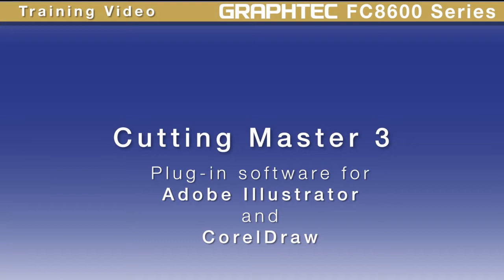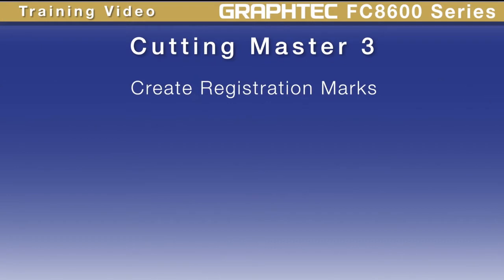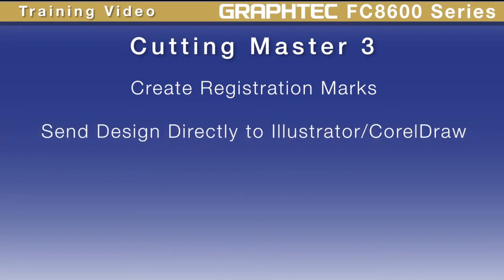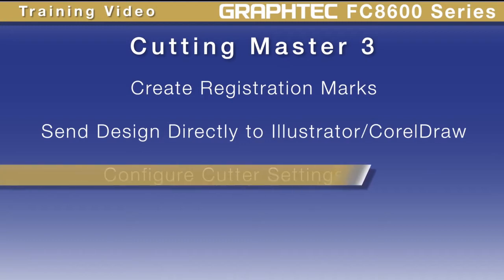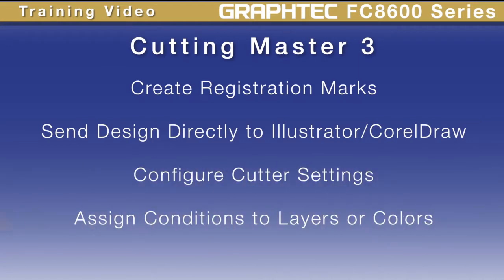The Cutting Master 3 application does several tasks. After creating a design in Adobe Illustrator or Corel Draw, registration marks for the print and cut process can be placed on the job design. The design can be sent from Adobe Illustrator or Corel Draw directly to the Cutting Master 3 application through the special Graphtec plugin that is added to Adobe Illustrator and Corel Draw. It is in Cutting Master 3 that cutter settings can be configured and adjusted. And conditions can be assigned to specific layers, colors, or whole job designs.